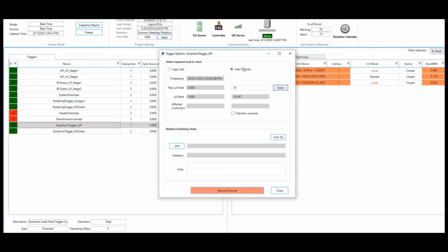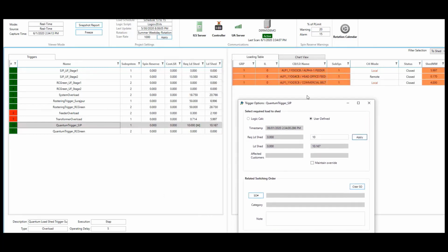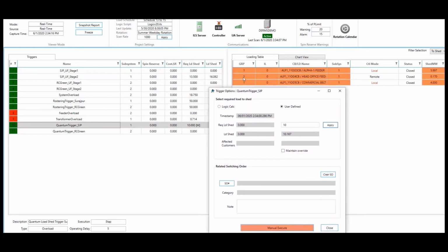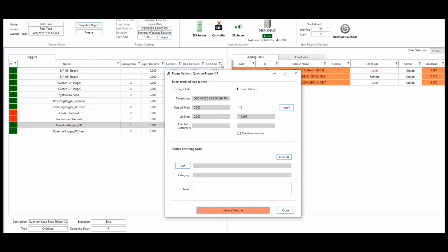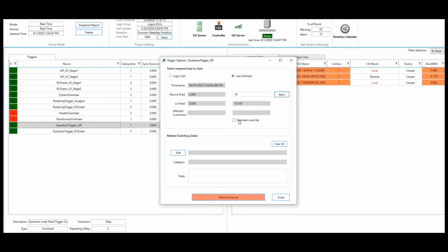In these situations, operators need to keep the system stable while dropping available load and protecting critical loads. In this example, we can see how an operator responds to unscheduled events and manually executes load shed in order to keep the system stable.